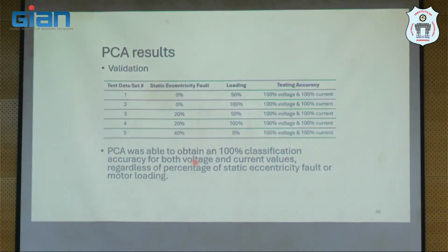So is the idea clear? All I did was I did Clark transformation. That's the only thing I did. After that, it is only covariance matrix, eigenvalue, eigenvector, transposition, and then classification is done based on generating the principal components.